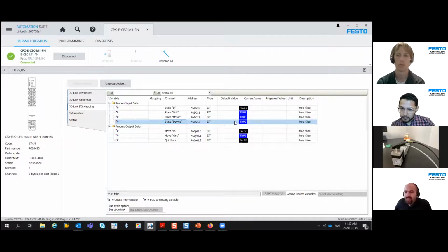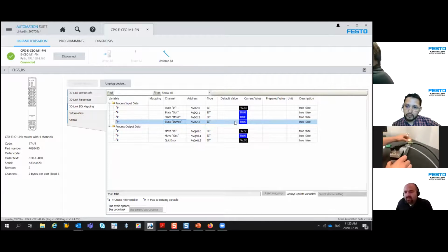Kevin, do you still monitor the actual position when the e-stop is pressed, or in this condition where the power is cut? Exactly. When you cut the power stage power, the only thing you lose is the ability to make it move. It goes into a floating state. So right now, because it's enabled, I can't move it.